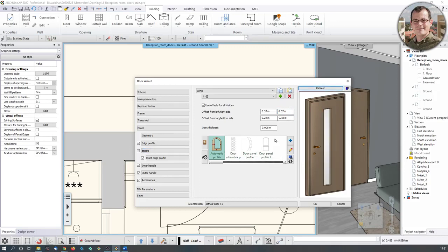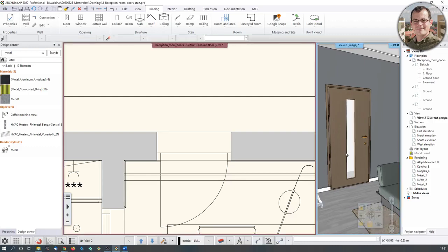So in this case, you don't have to add the width of the inset because the software calculates that based on the two sides values. Top and bottom offsets are good to go. So I'm just going to say, okay, that's good for me, and I have it like that.